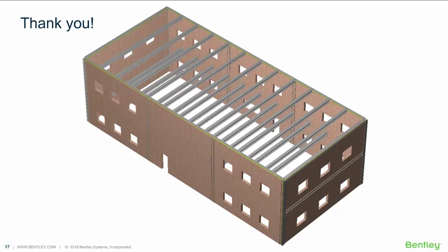There's one here, Josh, asking if there's a table for the roof deck properties. Okay, yeah, in RAM Modeler, when you specify a bare metal deck, you're just inputting basically the analytical properties. So the Young's modulus, the assumed diaphragm thickness. I don't believe it's read from a table directly as of now.